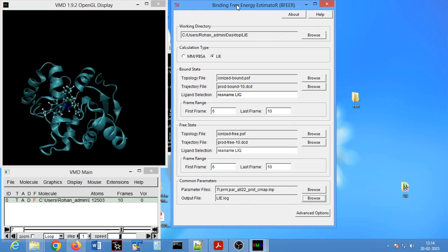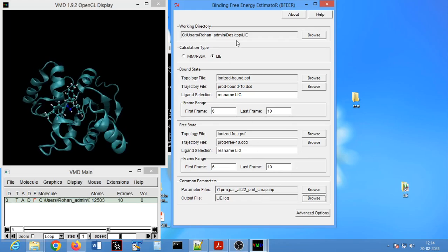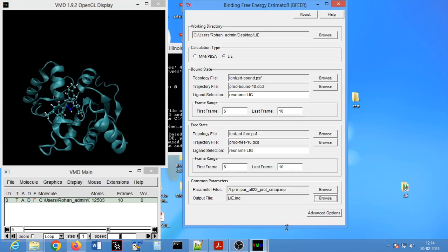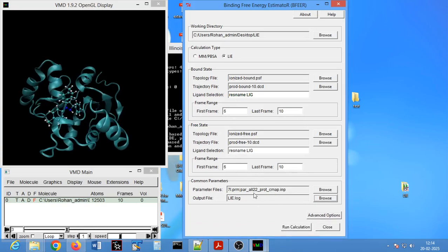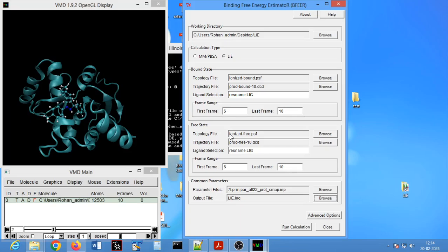By default, you can directly go ahead for running this calculation, but if you directly run this calculation at this stage, you would be using the default value of the empirical parameters alpha, beta and gamma. By default, the software utilizes the LI coefficient of alpha as 0.18, beta as 0.33